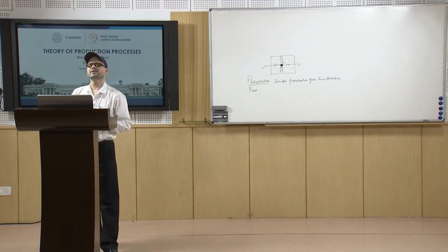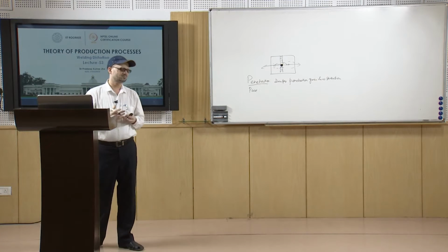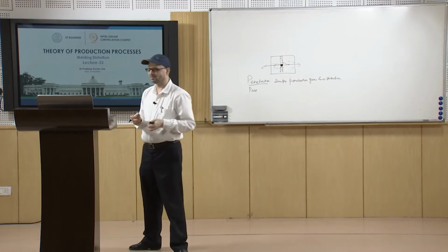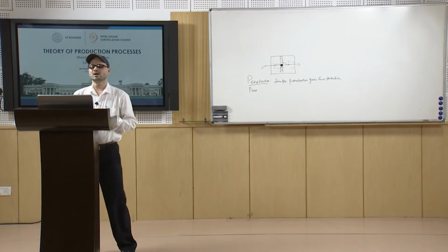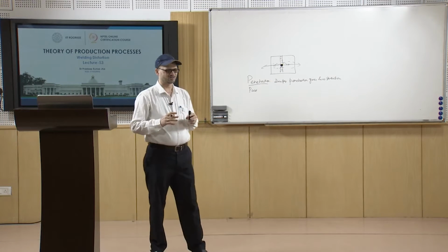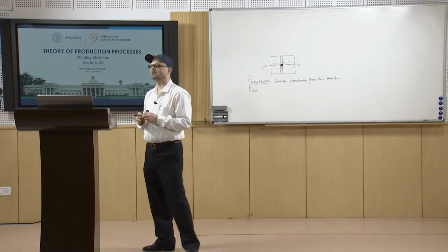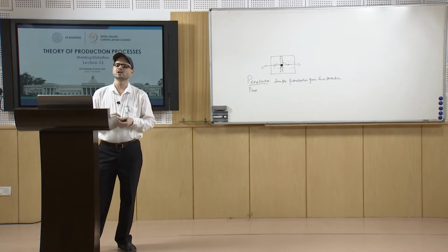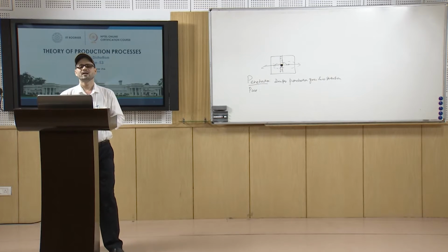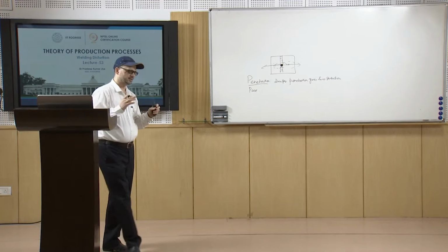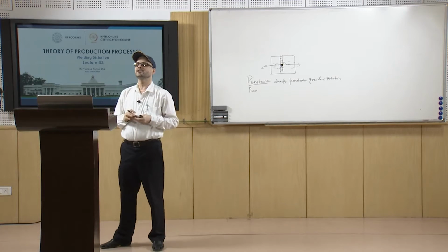Normally about 1/1000th of the weld length is the normal value of this longitudinal shrinkage, and it is very less as compared to the transverse shrinkage. There are certain formulas. Depending upon the current and the length of the weld, this longitudinal shrinkage varies.